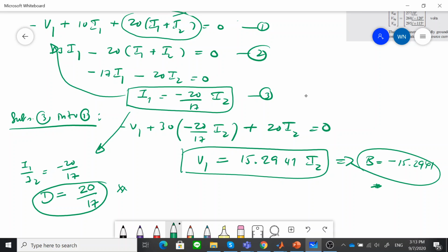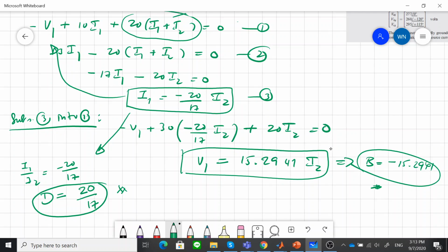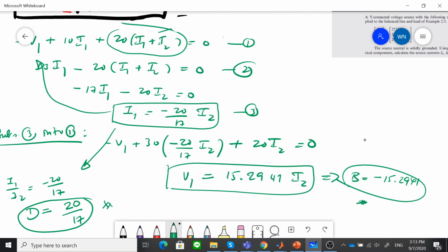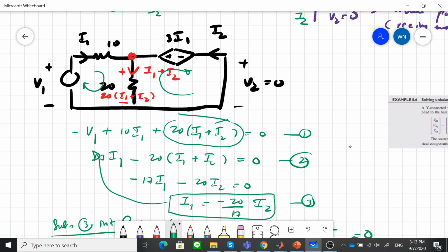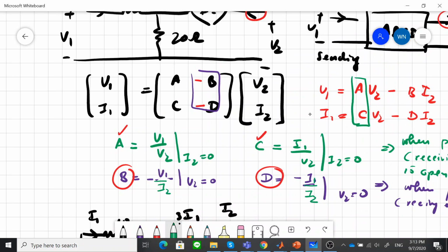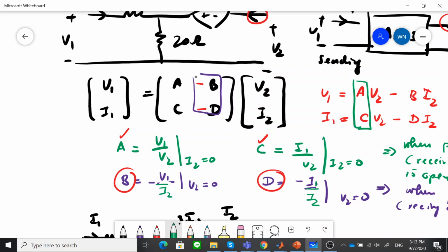All right. The nice thing about the two-port calculation is that when you know the voltage and current at the receiving end, because we need to map the relationship between the receiving end and the sending end, meaning if you could derive the transfer matrix like this, you just multiply the voltage and current on the receiving end by this transfer matrix, and you get the sending end quantities.